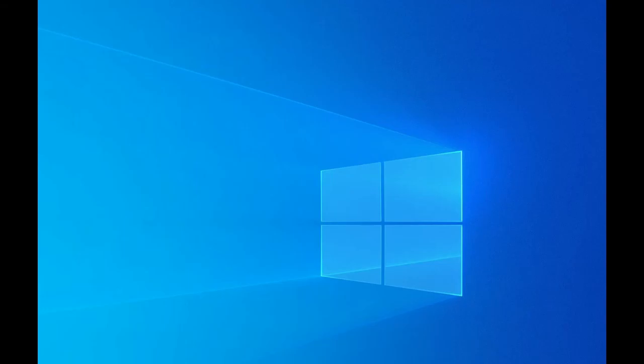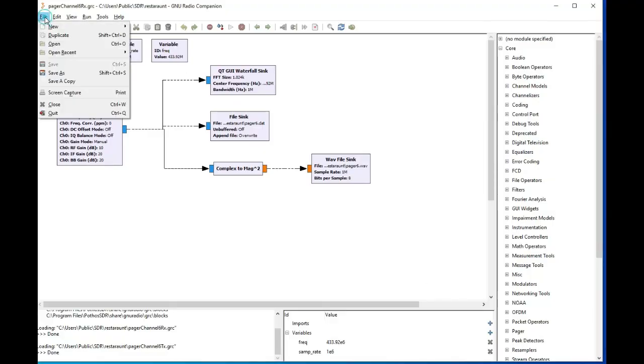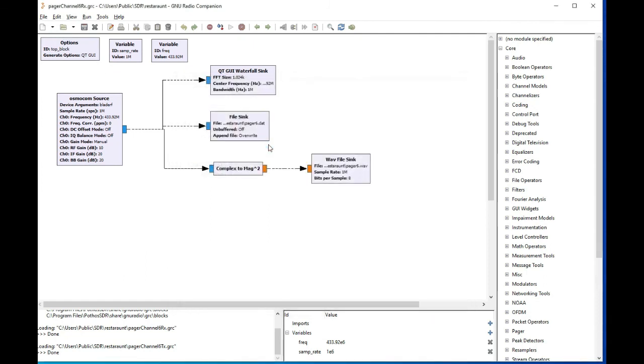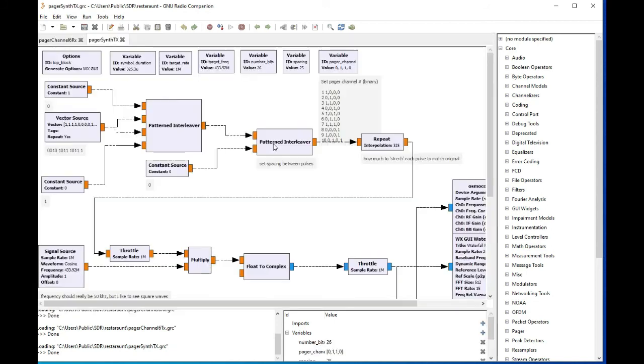So if you bring up the synthesized version I put together, let's go ahead and open that up. And this doesn't rely on any DAT files. The computer actually generates it for you. GNU Radio Companion. I know it's a little complex, but you see there's 4 inputs, like I said. 1, 2, 3, 4. And on the far left is the bit pattern that goes into those 4 inputs, and that determines the bit pattern that gets outputted.